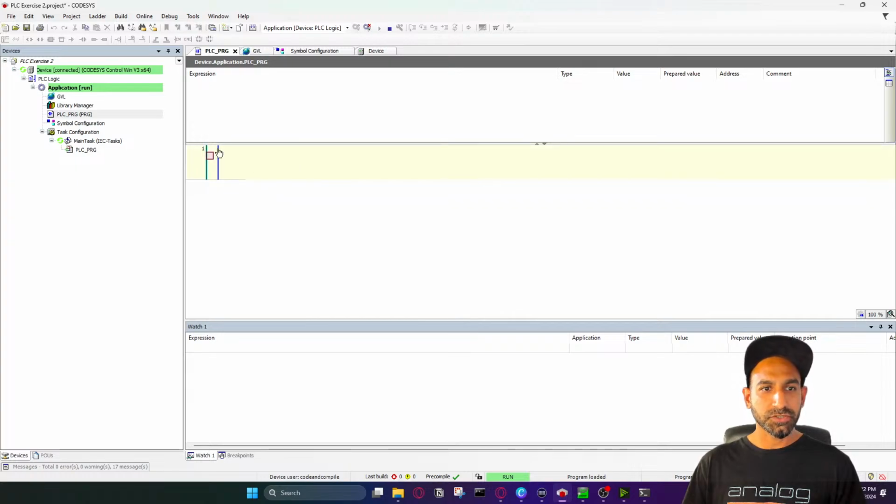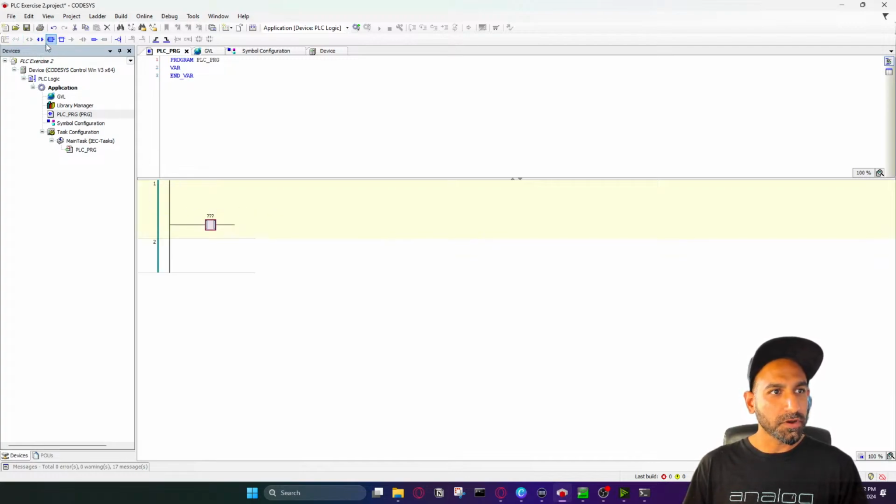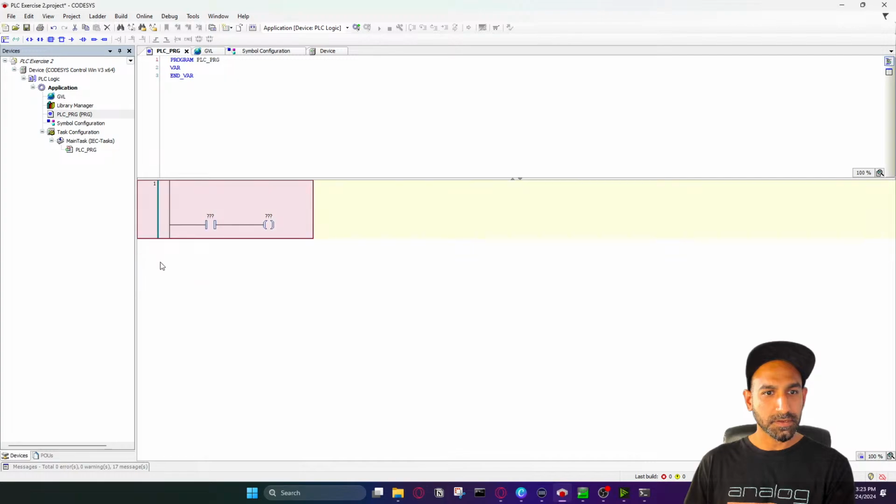In this case, you can go to your PLC program. Because I took the ladder logic, which I never used on CODESYS before, to be honest, I have to see how to use it. I believe this is your input contact. I've used ladder logic in other programs, but in CODESYS I usually do structured text. And this output should come here. Okay, this looks nice, and we have an input and output. Now, how is the input going to come here? We have connected the variables.